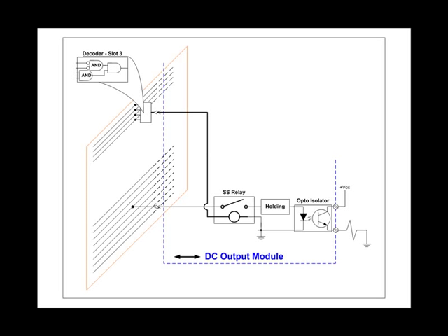This means that at any moment when the processor is working on the backplane, it is the processor and a single module that are connected. All of the other modules, while plugged into the chassis, are electrically unplugged by the bank of solid-state relays in each card that isolates the I/O from the backplane.